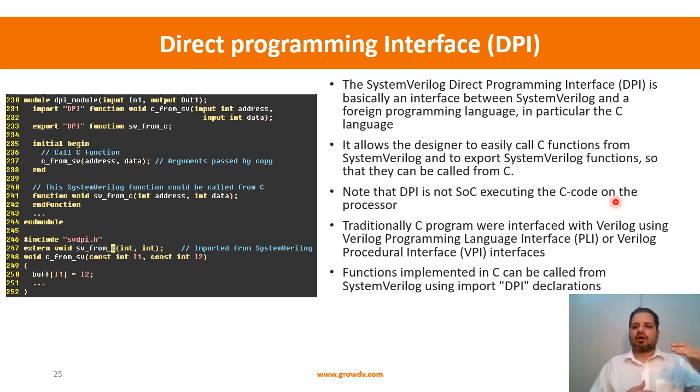They provide the formal definition of the algorithm, and along with that they also provide C code to make it clearer. These are error detection and correction mechanisms, encoding and decoding, that help you do single or multi-bit error detection. LDPC is one of those algorithms used in cellular communications and even in various storage drives. So you can take that spec-provided C algorithm and use it as a reference model.